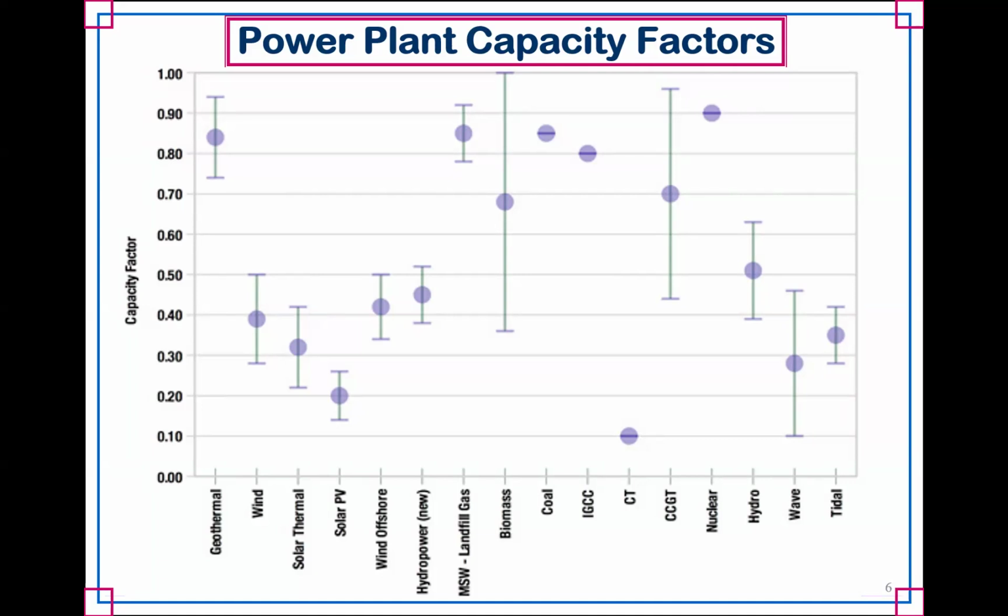But with that being said, these current generation nuclear power plants were designed so that they can't ramp up and down in power very efficiently. They do very well at getting up to full power and staying there. That's where they like to be. If you were to try to ramp a typical commercial nuclear power plant today, it would struggle with that.